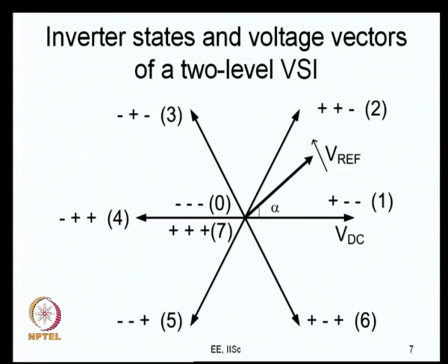Now, in space vector based modulation, you have a revolving reference vector. This revolving reference vector revolves at the fundamental frequency, and its magnitude is indicative of the magnitude of fundamental voltage that you want, and you sample it in every sub cycle. Once you sample it in a sub cycle, you produce it using a set of the nearest vectors.